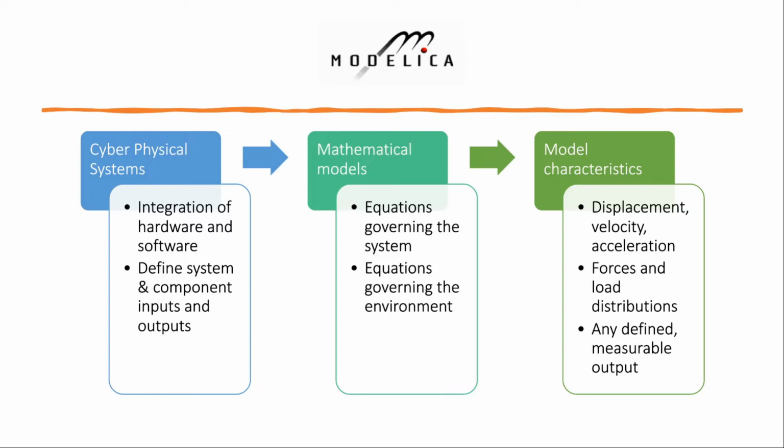This tells the solver how to link the spring to a mass and to the reference ground. Lastly, by solving the governing equations of each component and then analyzing the system as a whole from the relations between each model, the total outputs of the system can be determined. Any data that is measurable, continuous, and linked to a component can be provided by Modelica.